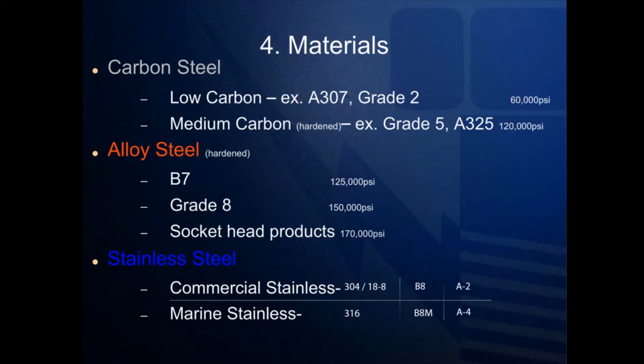Even the simplest steels would be composed of 99% iron and 1% carbon. However, the term alloy steel is the standard term referring to steels with other alloying elements in addition to carbon. Common alloyants include manganese, which is the most common one, nickel, chromium, moly, vanadium, silicon, and boron.